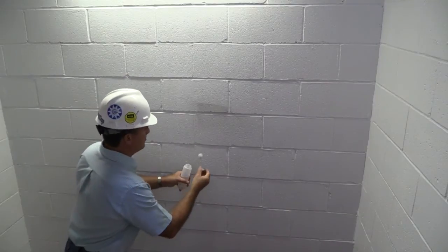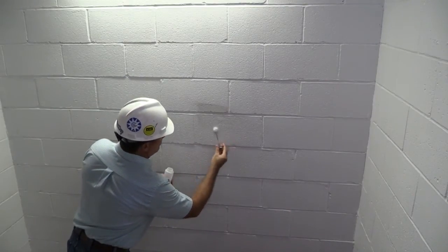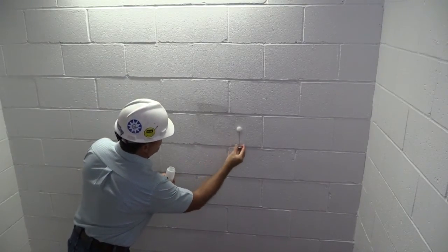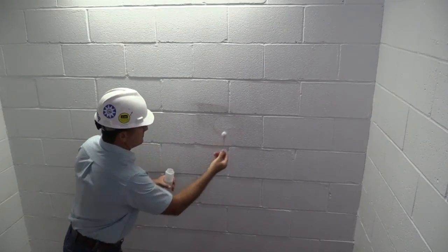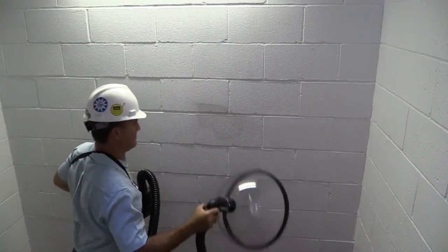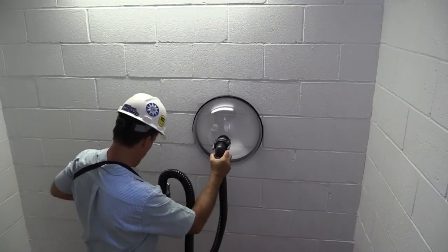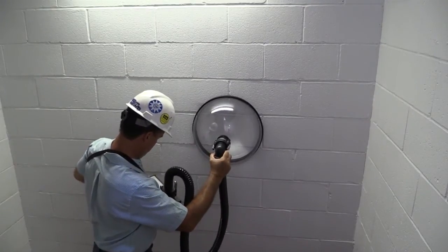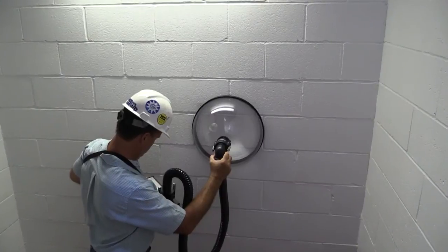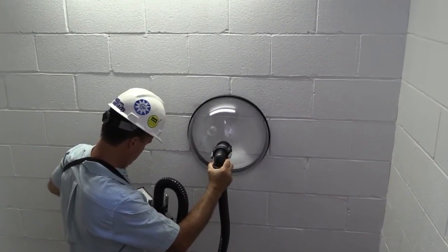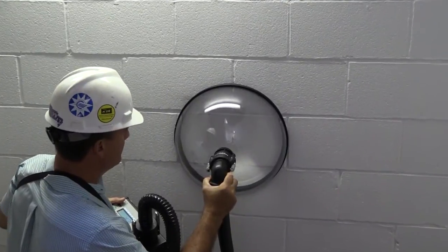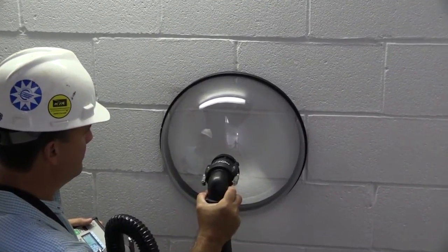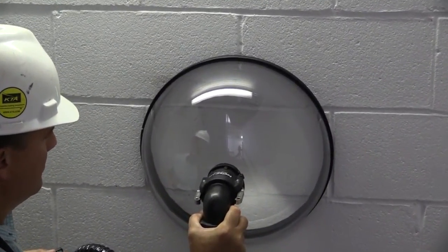Apply a thin film of the solution over the test area, but don't apply it too heavily, otherwise the solution could froth and foam. Once the solution's in place, hold the dome firmly to the surface. You don't have to push too tight to create a perfect seal because the fan will make up for the difference. But then push the green button once to activate the unit and a second time to start the fan.